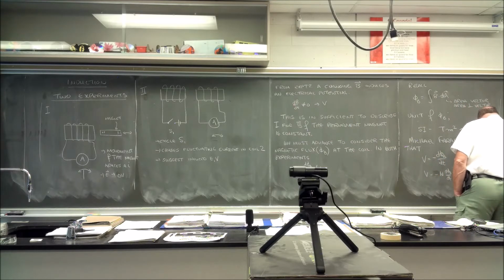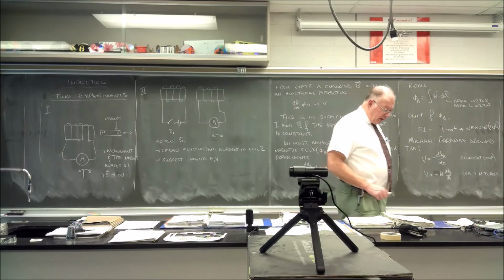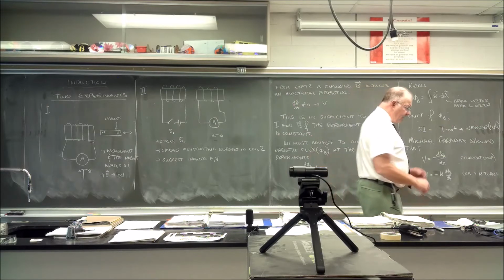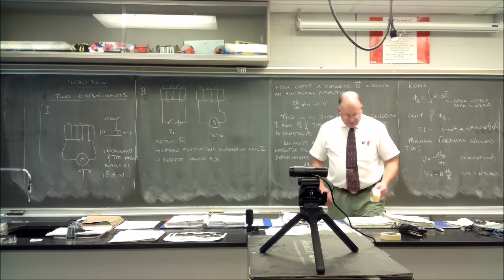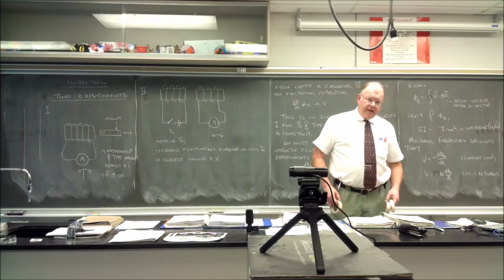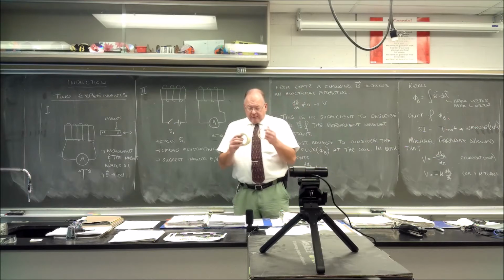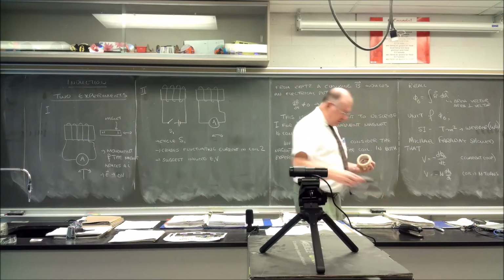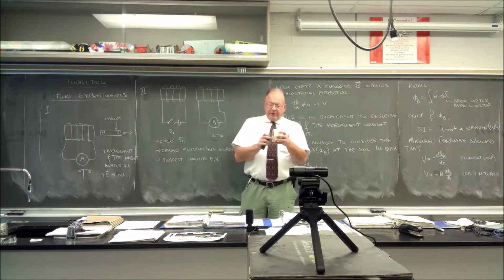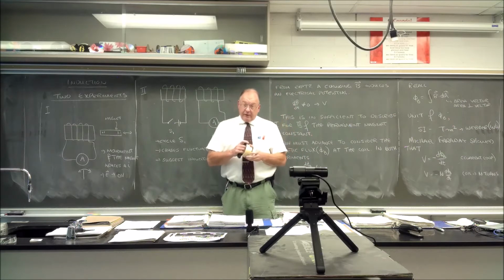So mercifully, as we add subsequent coils, it simply multiplies. Now that's a bit of a lie, because as you have subsequent coils, they're positioned in different locations. When you say that we can use N, we're implying that these coils are somehow on top of each other and superimposed, but really they're spaced out. So when the magnet is here, it's doing something to this coil, but it's going to be a different flux change to this coil. There's going to be a little bit of difference here.